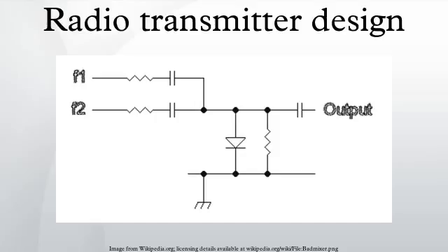Harmonics: these are multiples of the operation frequency of the transmitter. They can be generated in any stage of the transmitter which is not perfectly linear and must be removed by filtering. Avoiding harmonic generation: the difficulty of removing harmonics from an amplifier will depend on the design. A push-pull amplifier will have fewer harmonics than a single-ended circuit. A Class A amplifier will have very few harmonics, Class AB or B more, and Class C the most. In the typical Class C amplifier, the resonant tank circuit will remove most of the harmonics, but in either of these examples, a low-pass filter will likely be needed following the amplifier.